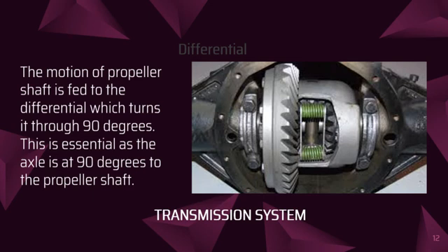As the automobile is to move as a single unit, all the four wheels must travel together. Therefore, the outer wheels should travel larger distance and inner wheels should travel smaller distance in the same period of time. Hence, the variation in the speed of inner and outer wheels is needed. This is performed by the differential with the help of sun and planet gear system.